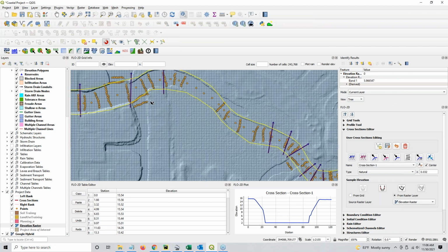It's kind of going up and down with those sandbars. But when the river starts to flow at flood stage, those sandbars are going to rework themselves and get mobilized and pushed around. So I'm not going to worry about trying to get a perfect cross section in relationship to those sandbars. I just want to get the capacity of the channel so that it can move water through the system.